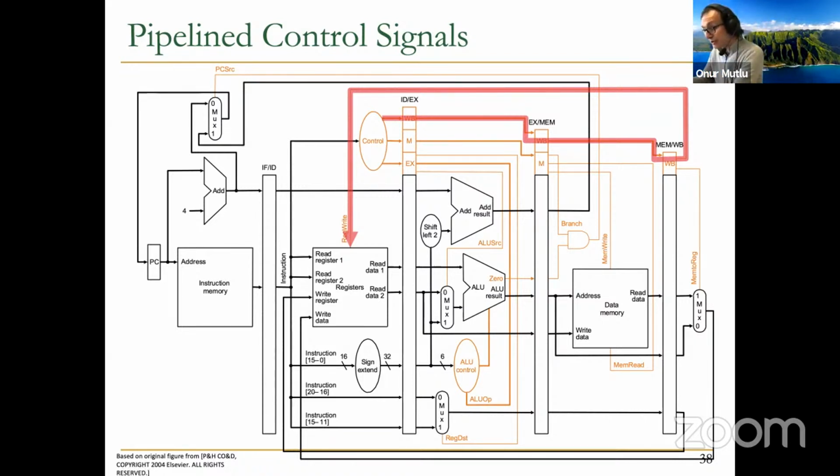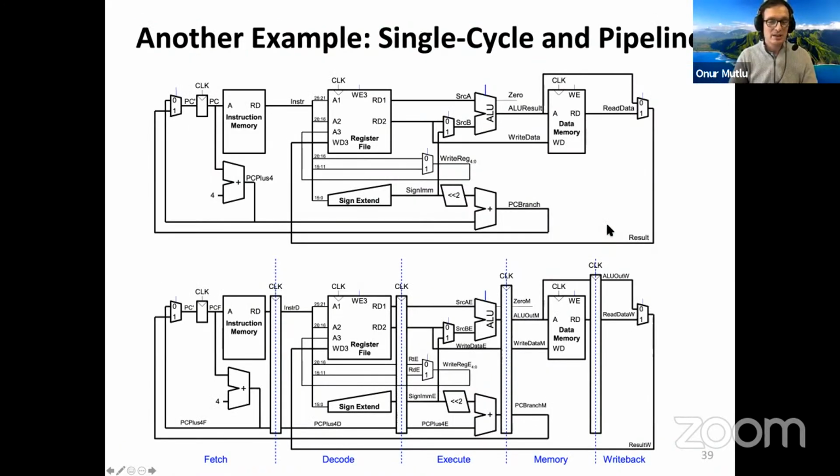And then we're also going to see how to make sure that that doesn't happen often, which is called branch prediction. Basically, we need to be careful about what to fetch after a branch. And that requires even more hardware, of course. But let's not get ahead of ourselves. That's a great question, and keep that in mind. You have a lot of issues with branches, as we will see. Of course, we're going to build up to that.